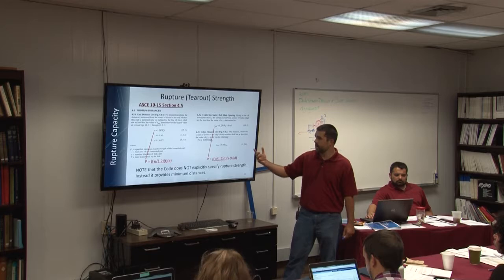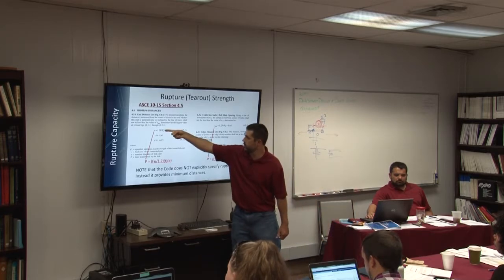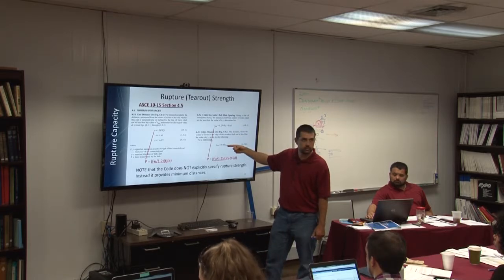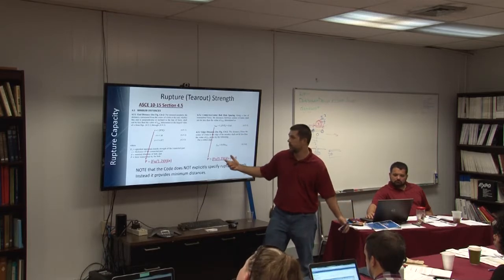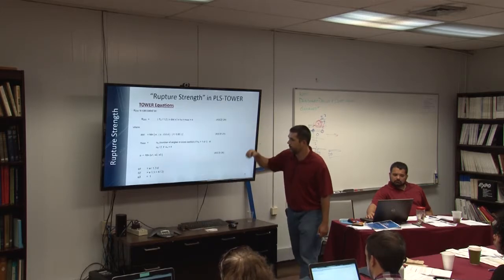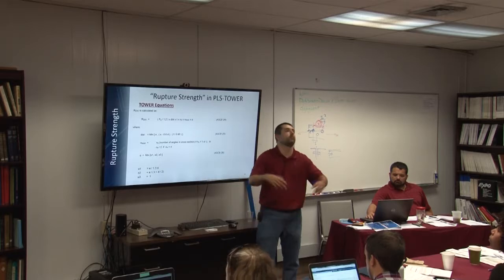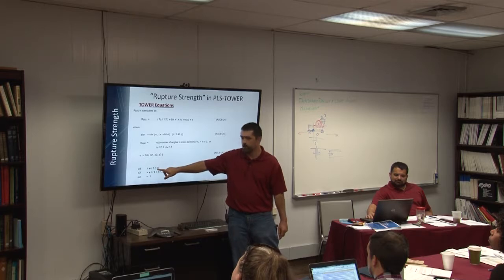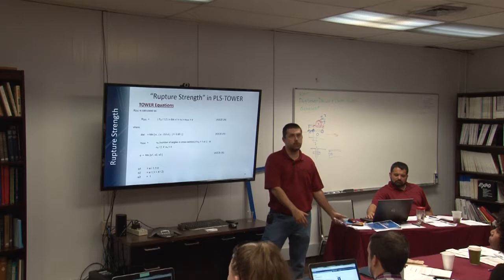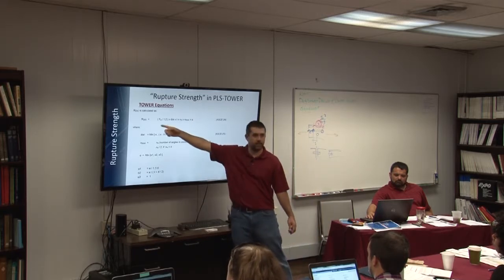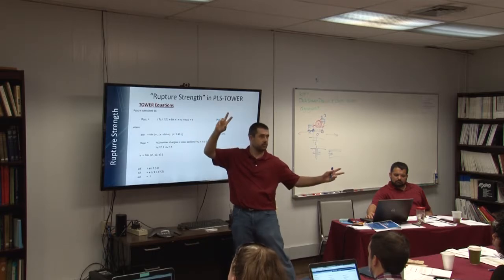So essentially, everything I've talked about so far incorporates this equation, and this equation, right? In a simplified, conservative manner. So what do they do if you don't meet these two? Can you go back? This alpha is like a penalty function. They divide your end distance by 1.3 times your bolt diameter, and if that value is less than 1, let's say it's 90%, then they decrement your rupture strength by that penalty function.